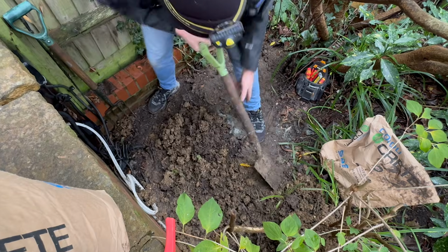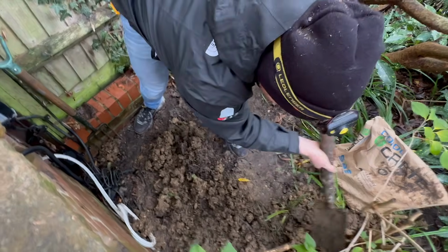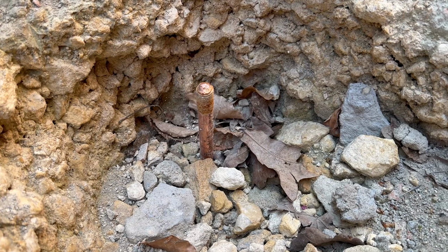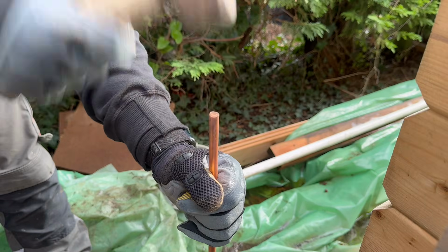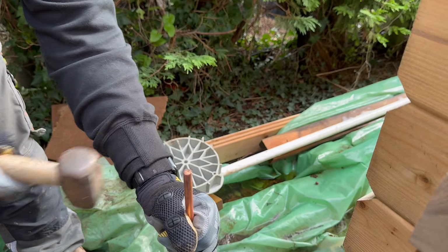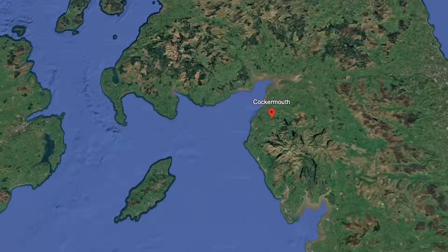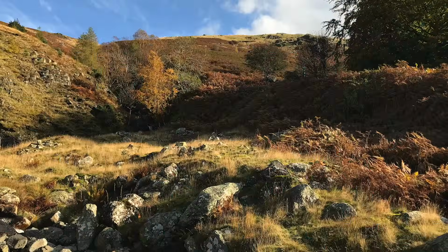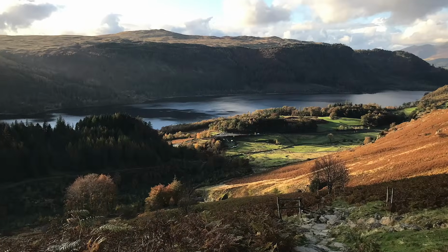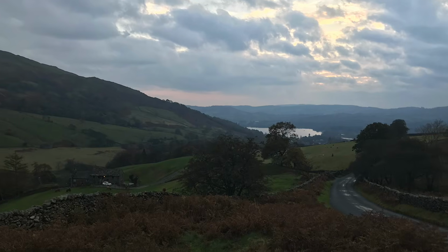Across the UK, the soil profile changes dramatically from region to region. This is why identical earthing systems installed to the same standard can perform very differently depending purely on location. Take somewhere like Cockermouth in Cumbria. This area is dominated by clay-rich soils with high moisture retention and relatively low resistivity. Current spreads easily, which often results in lower earth resistance values without needing excessive earth electrode systems.